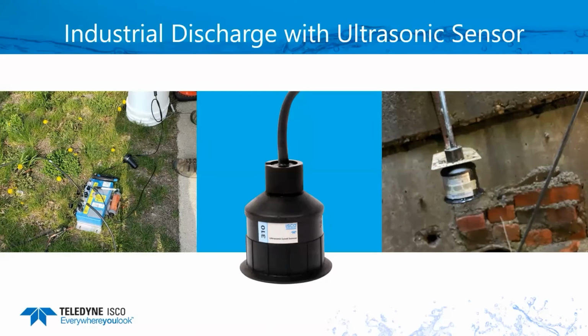Industrial discharge monitoring using ultrasonics. Another application that we will be heavily involved with would be just hanging an ultrasonic sensor over there to measure either water coming out of an industrial discharge into a flume, or maybe this is going to be an overflow indication.